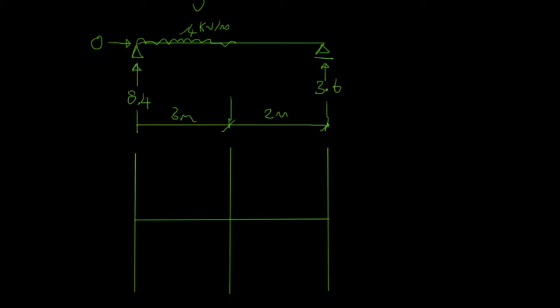Okay, and yeah, so we'll start here. And this is a positive axis, and this is the negative axis, and this is going to be 0 shear force. So it's a shear force diagram, and everything's in kilonewtons. Okay, so I like to work from left and go right, and that's pretty standard. So starting at reaction, we've got an 8.4 kilonewton force, well, reaction, pushing us up.